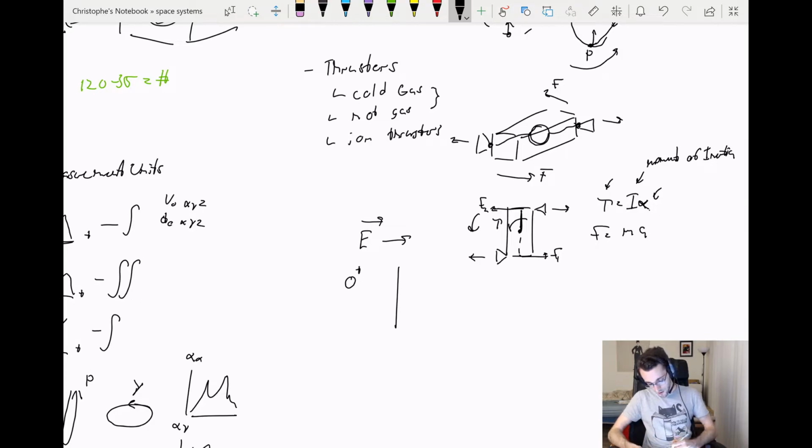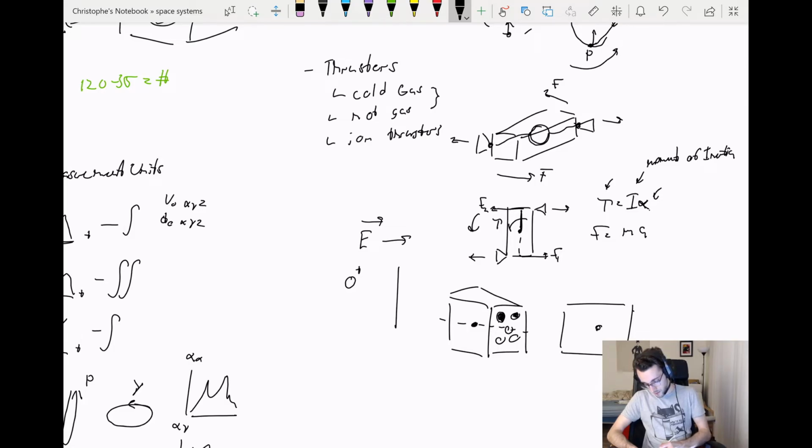But let's look at the back of our satellite here. Let's say you have like 5 thrusters, right? What you can do to induce a moment about your craft, and you've got your center of mass right here lined up with that central thruster, is you can say, oh, hey, if you fired these 2 thrusters at the same time, but not the rest of them. So looking at it sideways here, there's a center of mass, there are 2 thrusters,